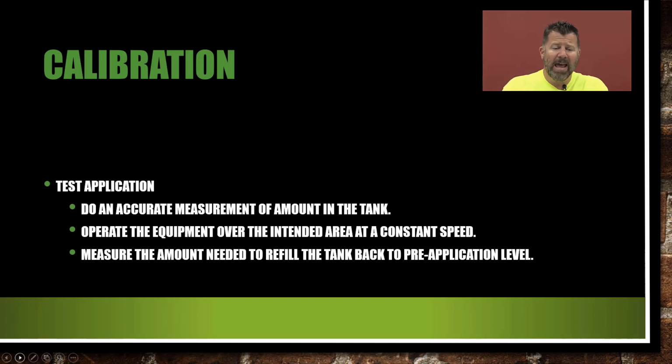Your test application, do an accurate measurement of the amount in the tank. Operate the equipment over the intended area at a constant speed. You can't hit the gas pedal, guys. You got to keep it steady. Measure the amount needed to refill the tank back to the pre-application level. And again, this should be done only with water.